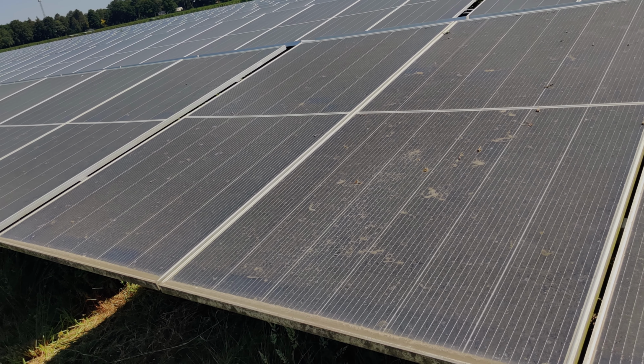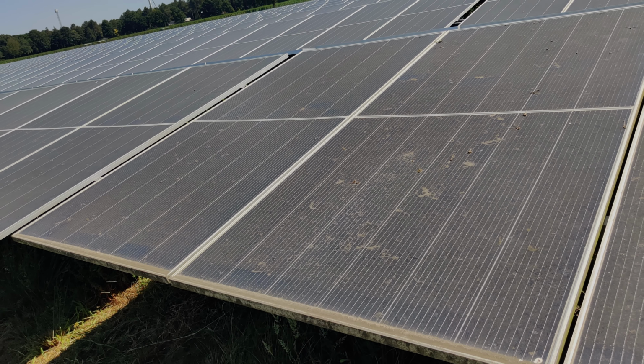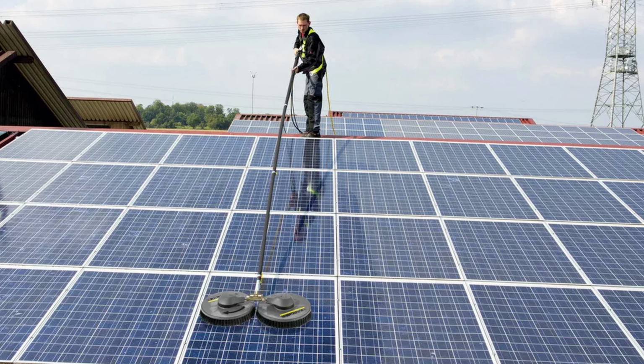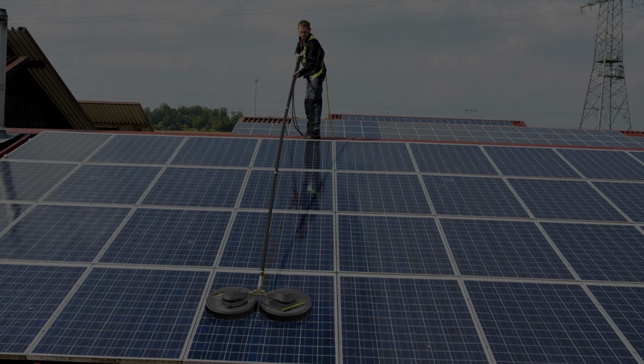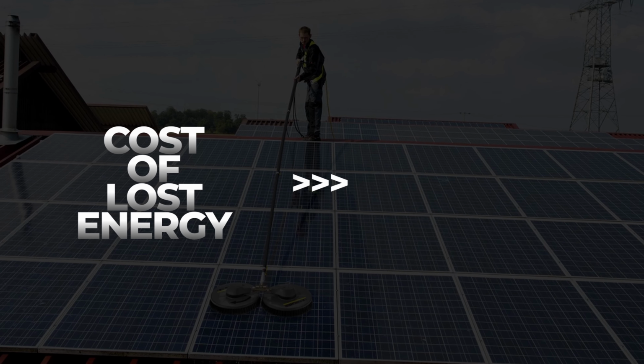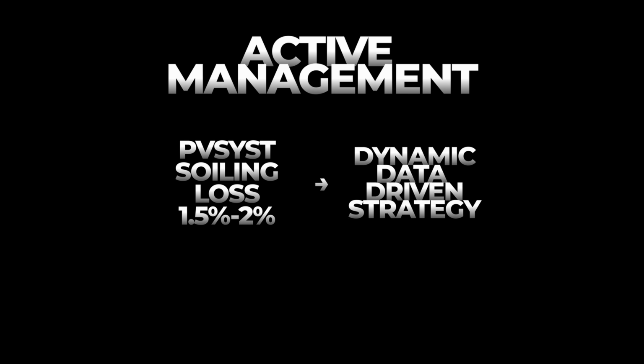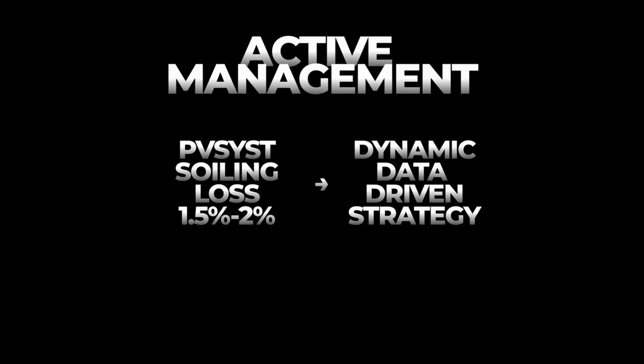That's why asset managers don't rely on assumptions. They track performance of the park to pinpoint the cleaning threshold. Cleaning is not about timing, it's about return on investment. We clean only when the cost of lost energy surpasses the cost of cleaning. This is active management, replacing PVsyst static input with a dynamic data-driven strategy.